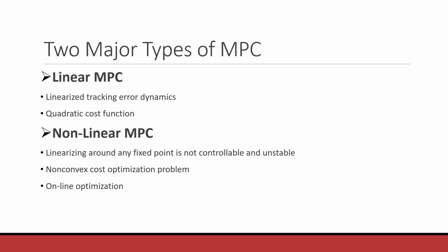When using low processing embedded systems, a local approach of linear MPC can be used despite the large tracking error. Mobile obstacle avoidance can also be included in the cost function by maximizing the distance between the robot and static obstacles. Also, saturation of the actuators can be considered in the linear MPC approach.